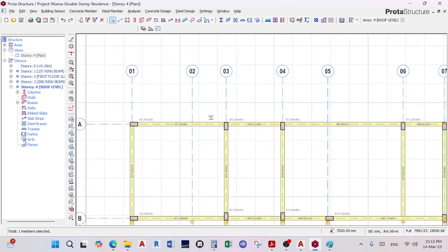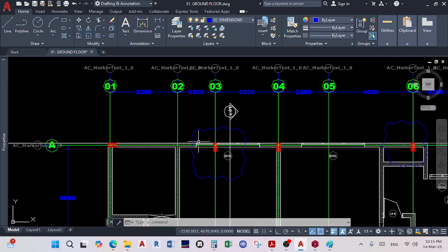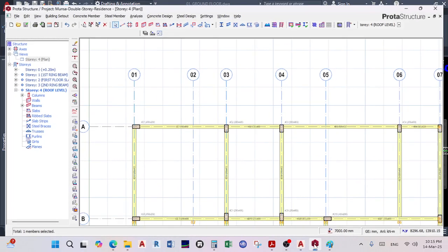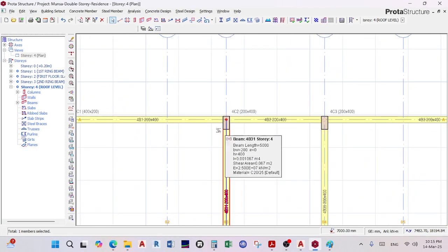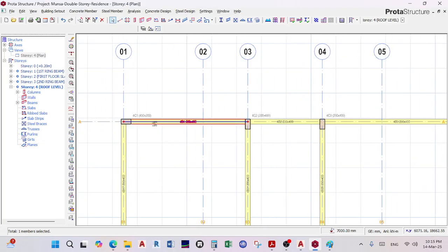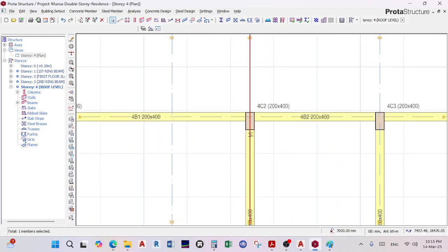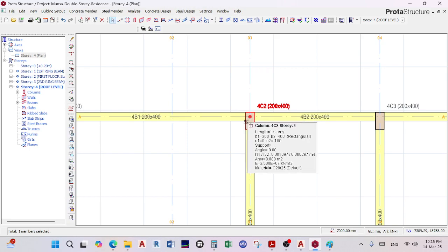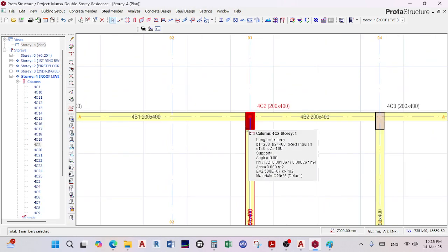Here I'll have to forgo 3A, essentially because it's sitting in the window, and then my roof slab can be supported by my blocks if I can solid fill them, right? Like I've seen generally, even Zesco does concrete slabs, but we use solid filled blocks. So this one I'll delete it.